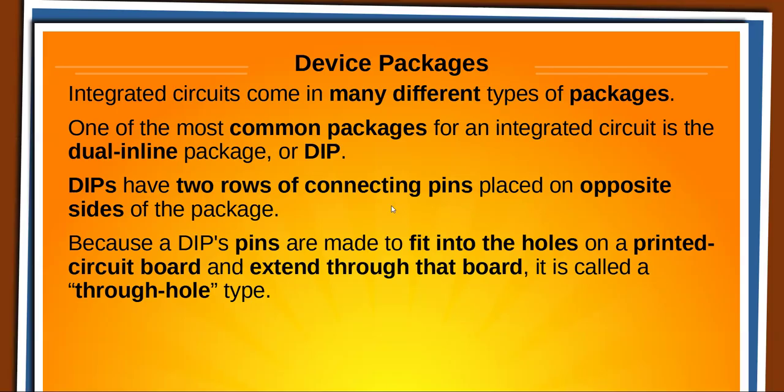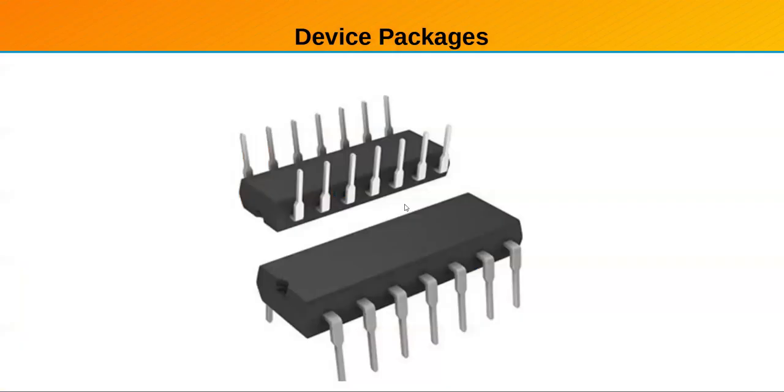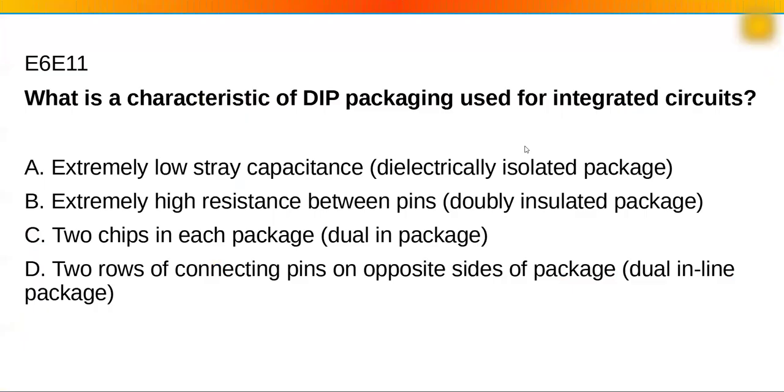If it's bad, it's easy because you just cut the pins and then take each one out individually. If you're trying to save it, it's a bear. This is just a picture of a standard dip. And the dead one, yeah, the dead bug. Are you familiar with dead bugs? I used to glue it on top of that one and then run wires. But I don't think their purpose was a dead bug, just showing you the bottom.